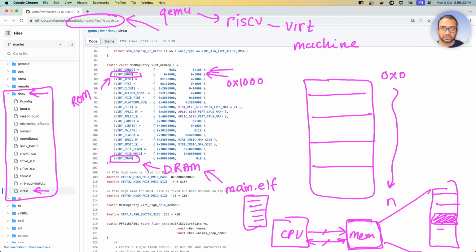So what happens is each machine, each embedded system will typically have some ROM. Manufacturers typically put their specific code there. And so the CPU will execute the ROM code initially, which I'll demonstrate now. And after it has executed that minimal code of initializing other things, it will jump to the code memory where the user's executable code is available. And by user, I mean the embedded programmers or another company's code.